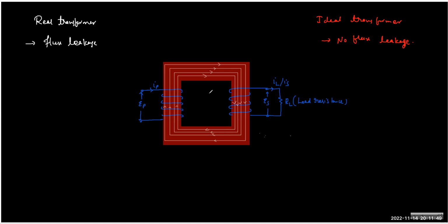So when you apply a magnetic field, the domains of the iron core will try to align themselves along the field. In the process of alignment, even if you remove the field, they will not become random to the same extent as they were. Rather, the removal of the field will leave the medium with some magnetism intact.